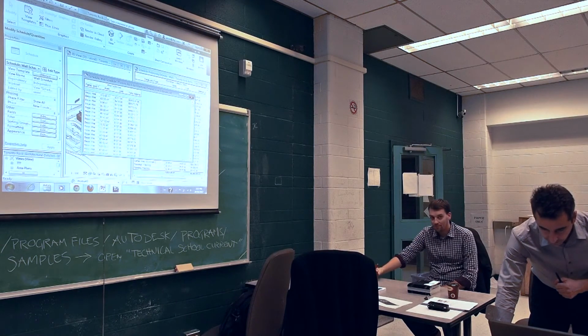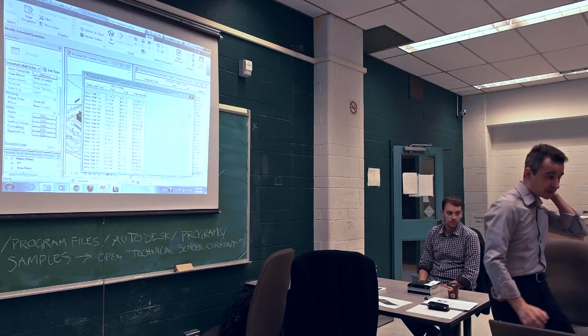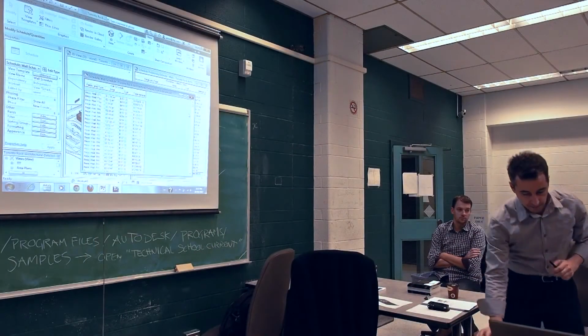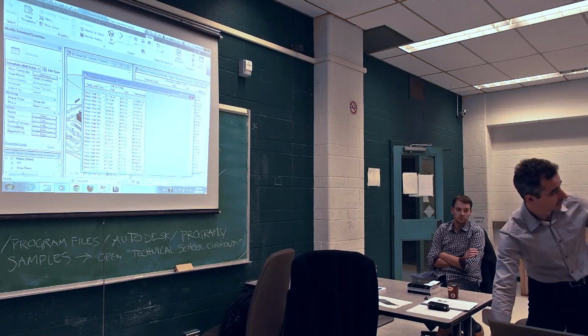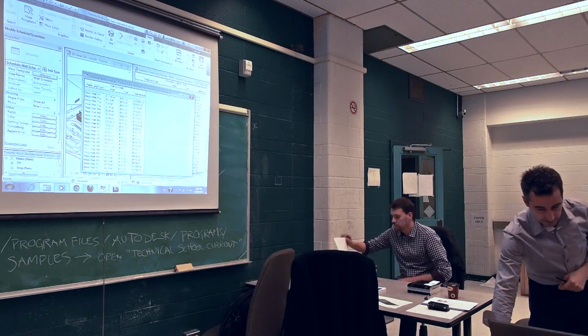It's a very long list of family types, area, cost, and total material. For the cost, you guys don't have anything, but we have it because we input the cost in here for each wall. And if you provide a cost of a wall, all the instances of that wall will take that cost. So I would actually add some cost in there. Before we do that, let's sort. So you will see that if you input a cost, it's going to go through the whole thing, right?